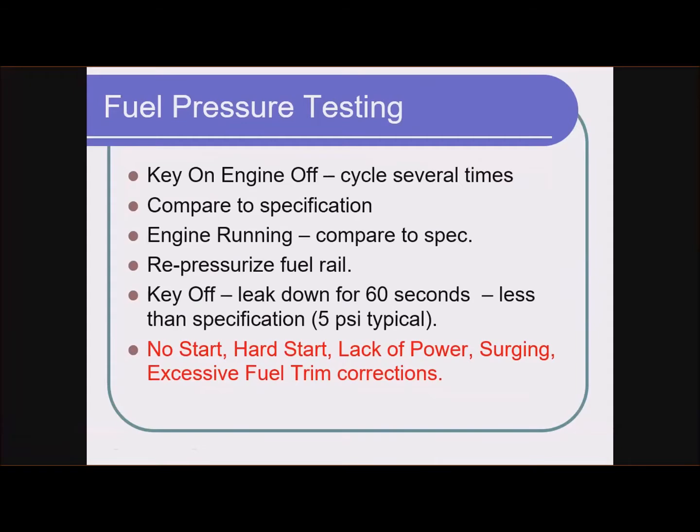So if you look at the symptoms on the bottom, no start, hard start, the ones in red, lack of power, surging, excessive fuel trim corrections. Let's talk about what could cause all of these things, all right? So no start, obviously, if our fuel pressure is significantly too low, the engine's not going to start. So, completely plugged fuel filter, bad fuel pump, a hole in the fuel line, something like that. Serious fuel pressure problem. We're going to have a no start.